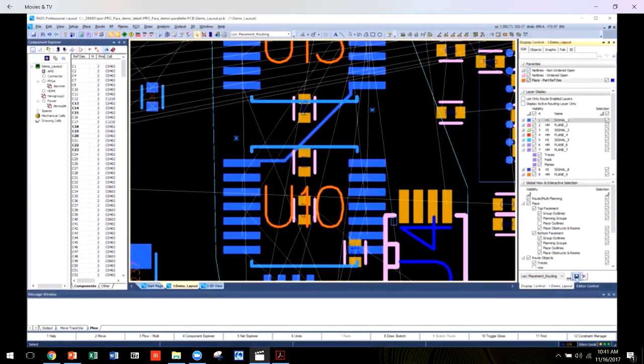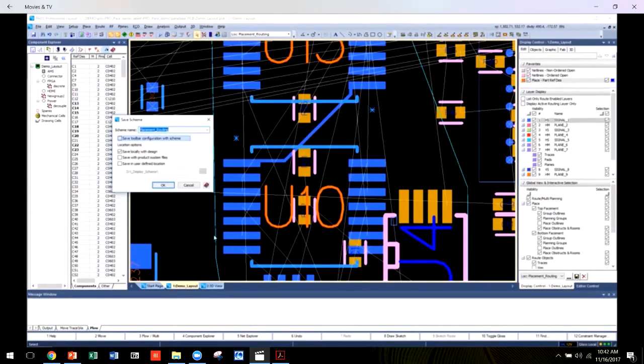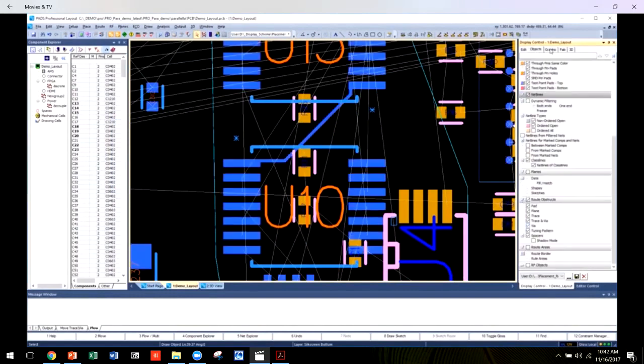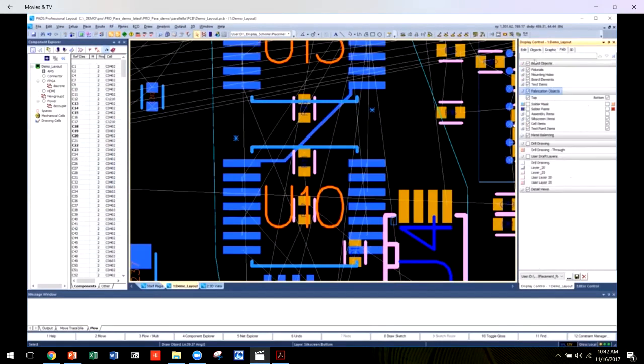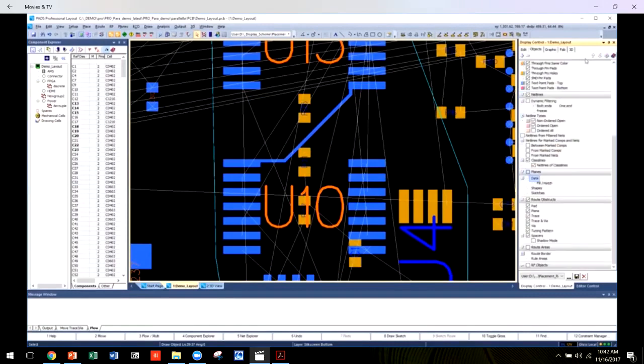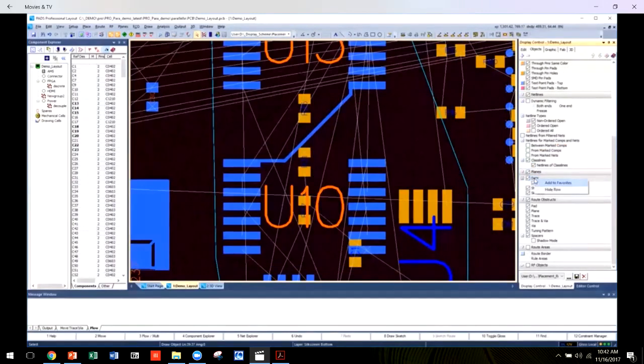You can change toolbar content and location by saving this information to your display scheme. Schemes can also be saved externally to be shared with other users. The purpose of a display scheme is to simplify your working environment and design flow, with display schemes independently controlling visibility and selection of task-specific objects, such as routing and fabrication objects. Filter out the unnecessary objects and commands so you don't have to fiddle around with the GUI. You can now spend more time using the tool and not fumbling around with the GUI looking for that one setting or switch. Make sure to take advantage of setting up your display scheme's favorites bar.